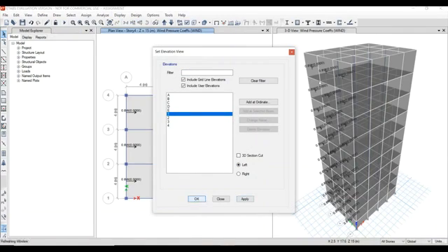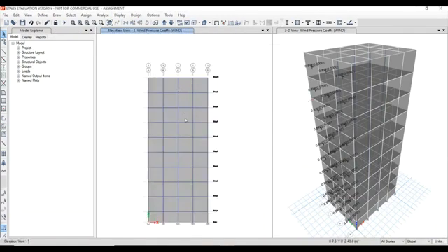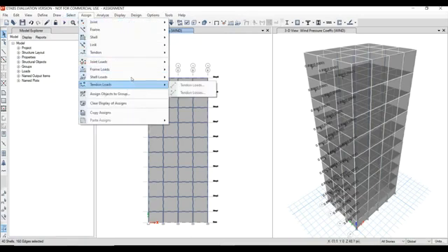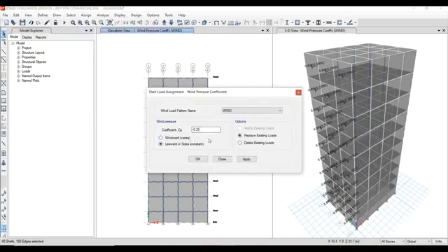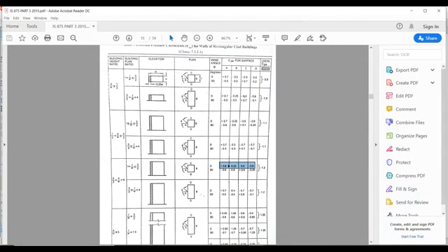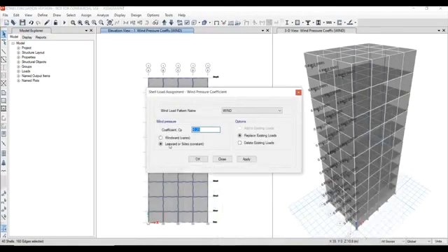OK. And now click every shell. So that we need to select it, and now we need to add, assign shell loads wind pressure coefficient, and for the wind pressure coefficient we have minus 0.8 and minus 0.8. So minus 0.8 leeward direction or sideward constant. Okay.